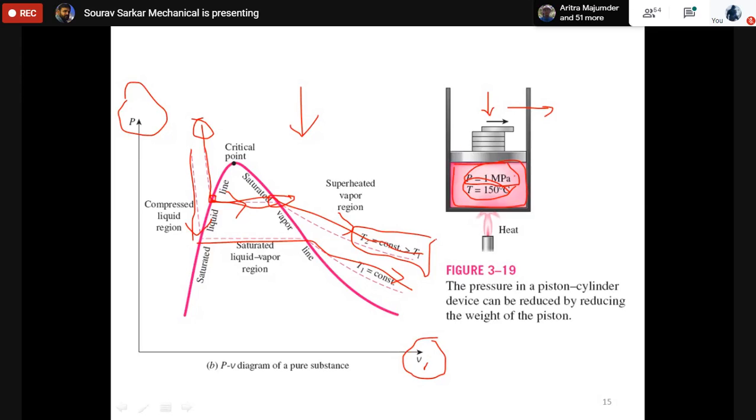That boiling is sometimes called cavitation. That is basically a word used in industry. It may happen that at 40 degrees temperature, at the exit or inlet of a pump, a phase change can happen due to low temperature and also low pressure. That is basically called cavitation. I am not going into that, but I am trying to say it happens.